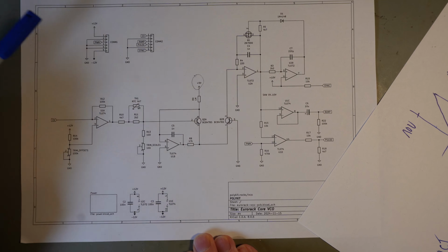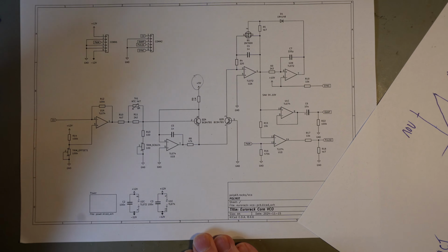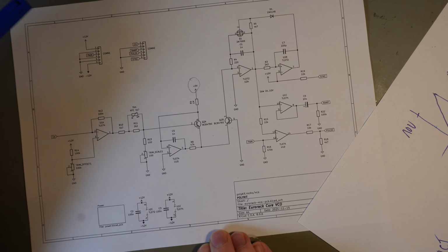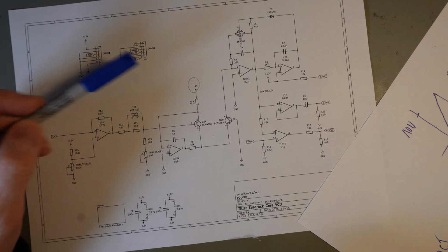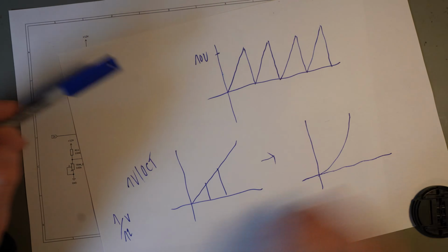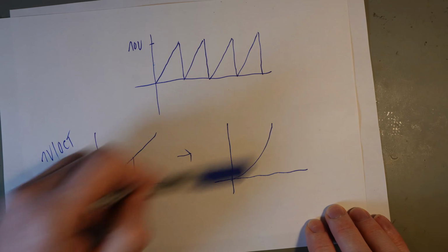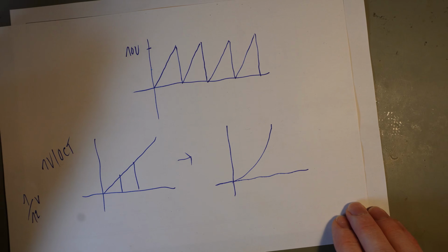So this is 2 transistors in one package. The idea behind this is that the transistors are on one silicon wafer, and that they have a very close matching. This works actually pretty well. So I get a good tracking like this here for over 5 to 6 octaves.